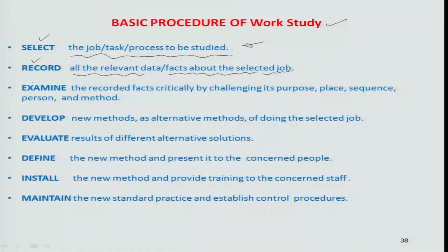So once that recording is done, then you want to examine. So basically you lay out all recorded tasks in terms of their times and their motion sequences, and try to record facts critically, and that is possible by challenging the purpose. Okay. So there are certain questions that I will present at the end of this presentation, which ask: is the task very important, can it be combined, can the task occur at a different place or a different instance of time, can it be carried out by the same operator or a different set of operators. These are the sort of questions which enable fitting the right task to the right person at the right time, so that there is an optimization. So this is all a part of the examination process.